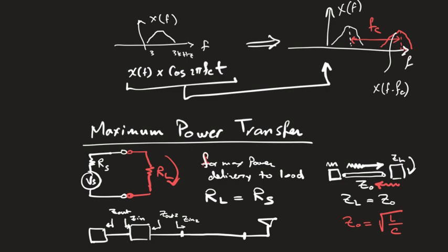If you are designing a component that you want to put into the market, then not only will you focus on what it does to the signal, for example, amplify or whatever, you have to also make sure that from a circuitry point of view, its input impedance and output impedance is 50, so that you can sell it as a standard component into the market. Okay? So that's one important thing. You have to make sure that things are all matched when you are designing an RF chain, whether it's a transmitter chain or the receiver chain.